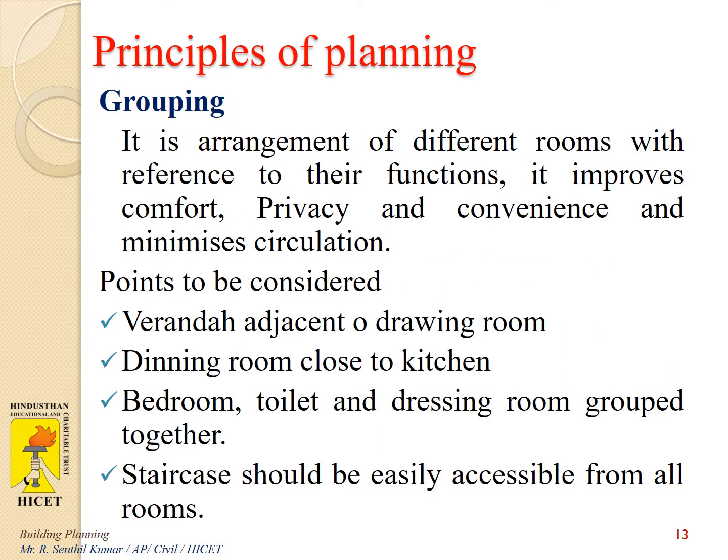And then grouping, it is the arrangement of different rooms with reference to the functions. It improves comfort, privacy and convenience and minimizes circulation. The major points to be considered for grouping action: the veranda adjacent to the drawing room and the dining room close to the kitchen, and then bedroom, toilet, dressing room grouped together, and the staircase should be easily accessible from all the rooms. These are all the grouping. Each and every component can be grouped together.